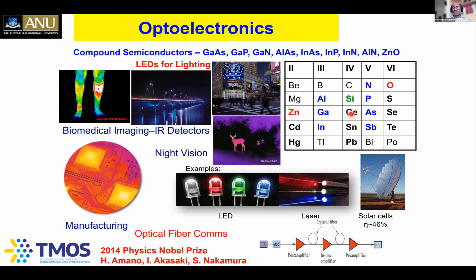But with multi-junction solar cells made out of 3-5 semiconductors, you can really reach now 47 to 48% efficient solar cells. And these solar cells have been developed for space applications, and generally these are expensive. But since satellites are so expensive, you want to have the most efficient solar cells. But also these solar cells made out of 3-5 semiconductors are also radiation hard. That means in space, when a lot of cosmic rays are hitting these solar cells, they'll be able to last a much longer period than silicon solar cells, for example.